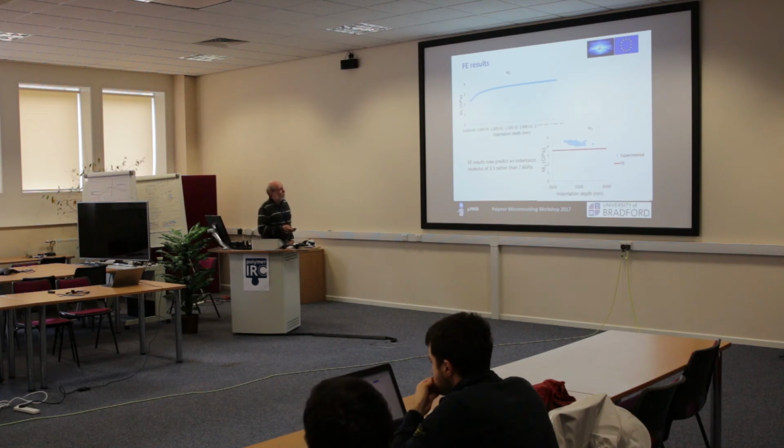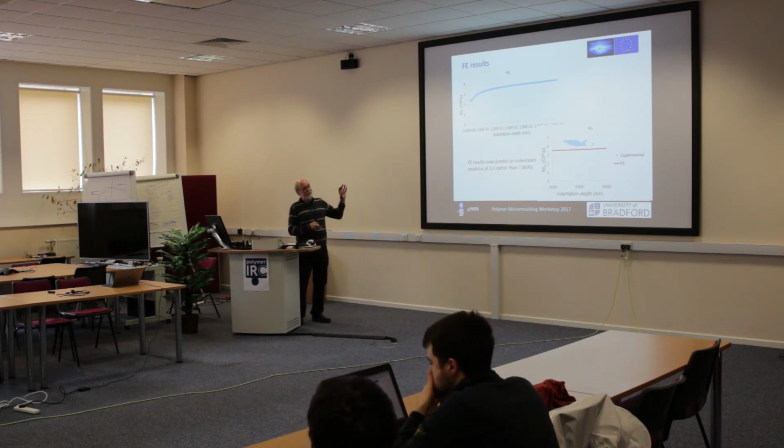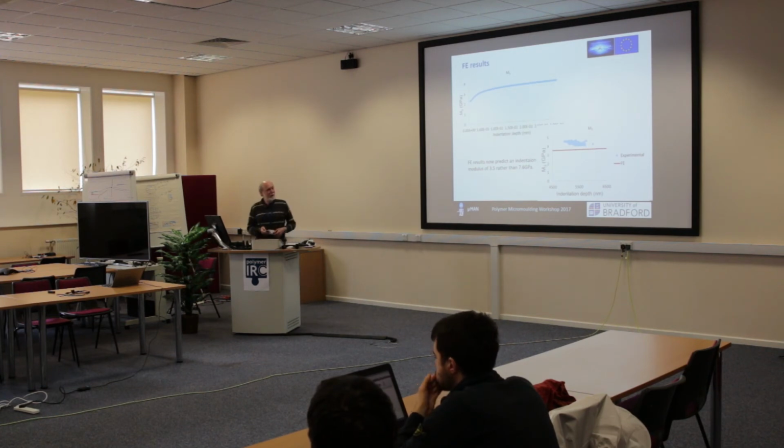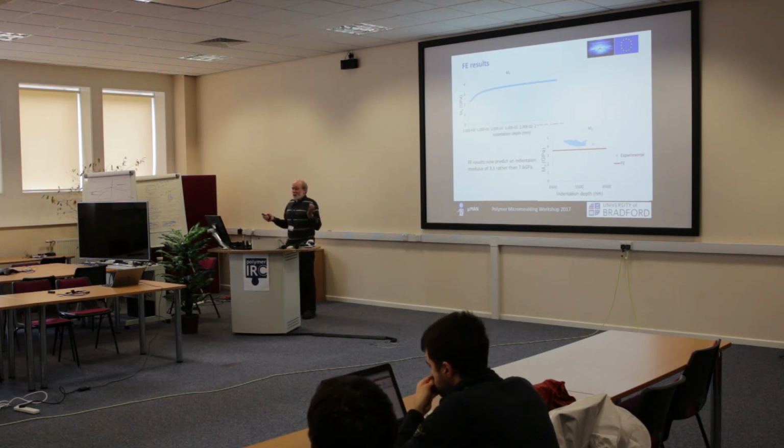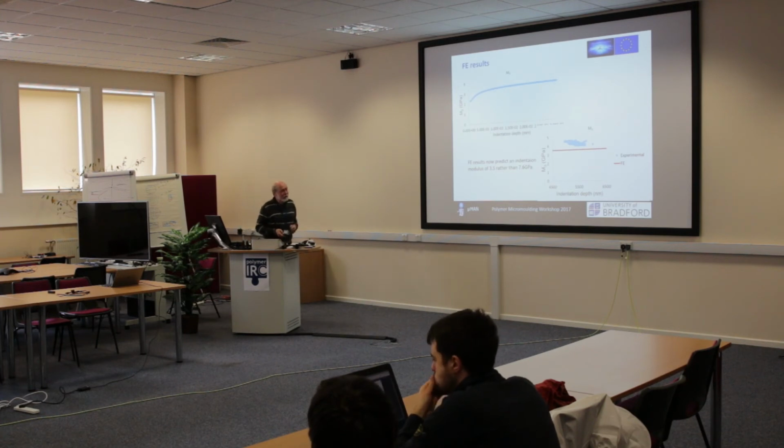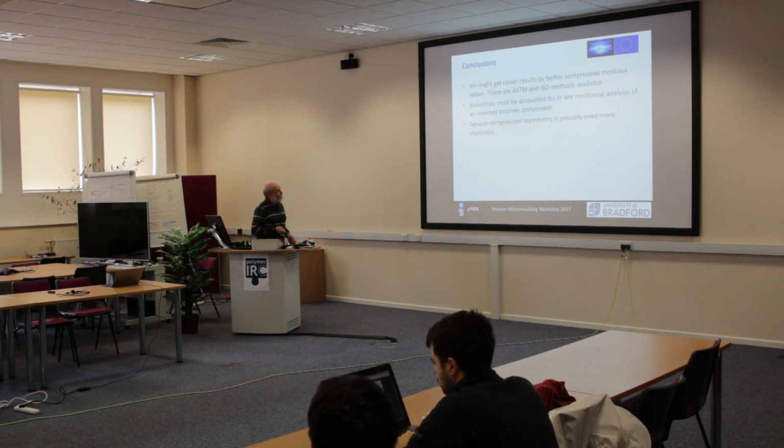Okay, so I think we're at the heart of the problem there. It is the difference between the tensile and compressive behaviour of the oriented polymer. No one really talks about the compressive modulus of oriented polymer, probably because it's not much to shout about. We don't orient polymers to improve their compressive behaviour, but we've got to know all the numbers. We've got to analyse oriented polymers properly and predict their behaviour as a component.